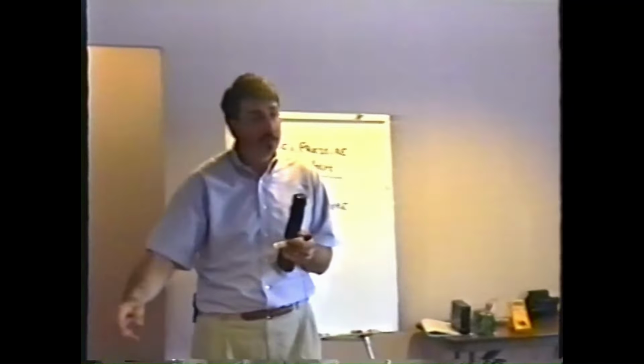All right, now put on your thinking caps. How about this one? Suppose we have one that is brown, black, black. Brown, black, black. What do you suppose brown, black, black is? What do you think? 1 ohm? Anybody think anything else? 100 ohms? Anybody think anything else? What was that, Dan? 10 ohms? All right, how many think it's 1 ohm? How many think it's 10 ohms? How many think it's 100 ohms? Who thinks it's 10? Okay, 10 ohms is correct.